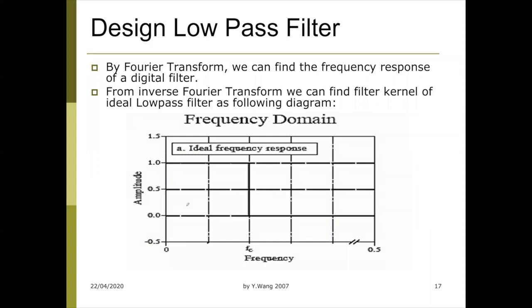So I'm going to give a talk about a couple of fundamental, basic filter design methods. People still do PhDs or research in this area, but understanding those fundamental filter design methods is a foundation for any advanced way. That's why when you're doing MATLAB, you can select from a range of different methods. Those are classical methods. Okay, so we're going to first talk about FIR filter design.